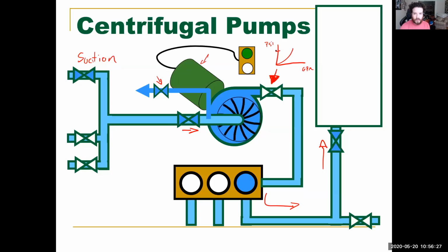All right, so we're at this dash mark right here. So we're going to slowly open up that valve. The reason we're going to do that is that we're giving it time to prime itself with our priming line right here. This is like salt water in. What it's using is saltwater pressure to put into the eye and fill up this casing, and then as soon as it has that, it can draw a suction. It's just this casing needs to be filled with a fluid.